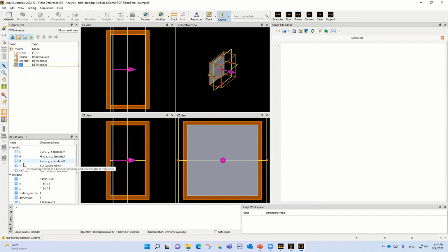So in this workflow, we start with Lumerical Mode, we simulate the mode calculation, and we export the mode to Zemax, to the free space. In free space, we do some simulation based on physical optics, and then after ray tracing, import it to Lumerical Mode and Lumerical FDTD. In Lumerical FDTD, we see which information we have: electric field, magnetic field, and all of the information that we can use to write our script and do our simulation.